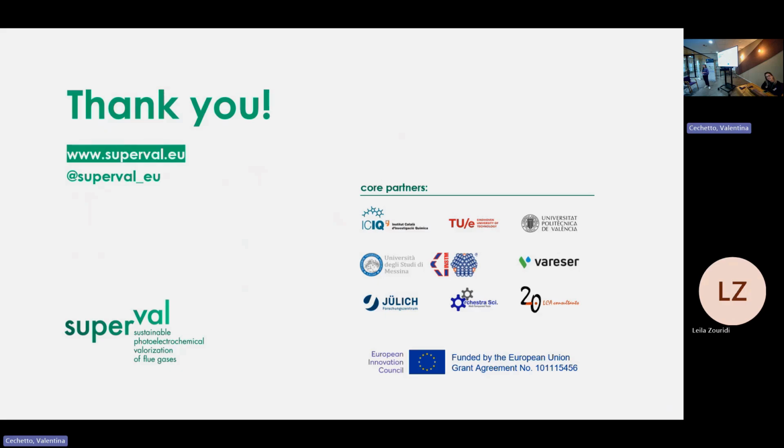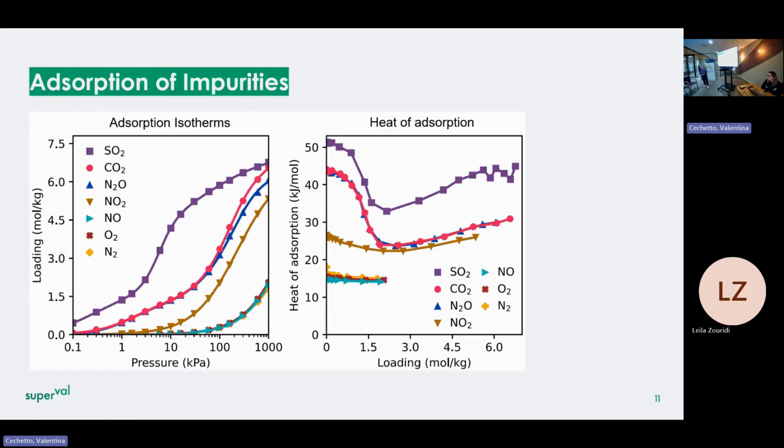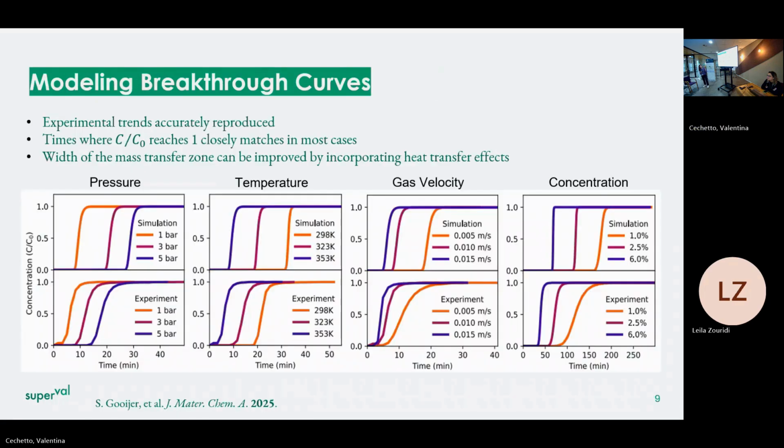I'm wondering, you did the modeling of experimental data of your partners, right? Was this experimental data on a powder, on pellets, or on shaped material? Yeah, so in comparison with the breakthrough, the plots I've shown are with powder. Now the experimental people have made the pellets, and we are now also doing the comparison with the pellets. Probably your saturation loading is lower with the pellets, so we'll probably apply a conversion factor on the isotherms and then model it like that.